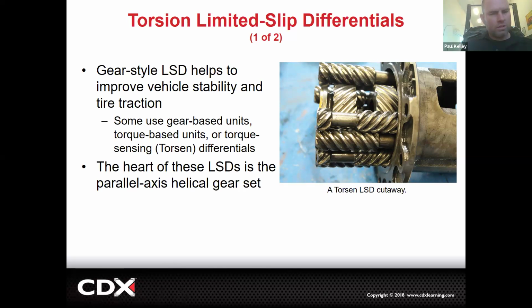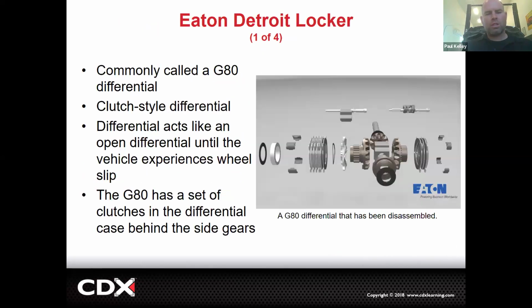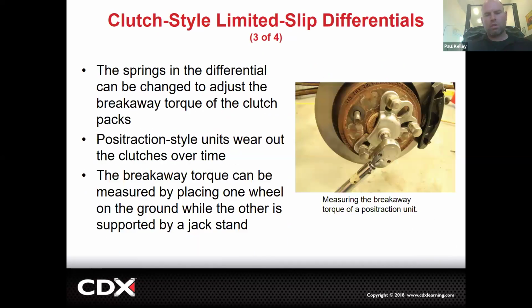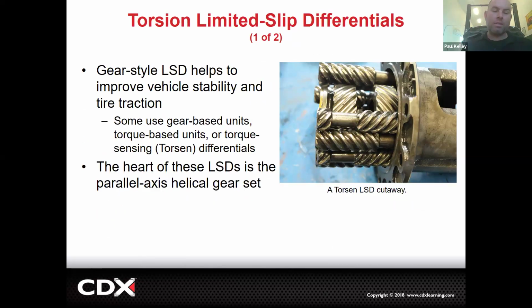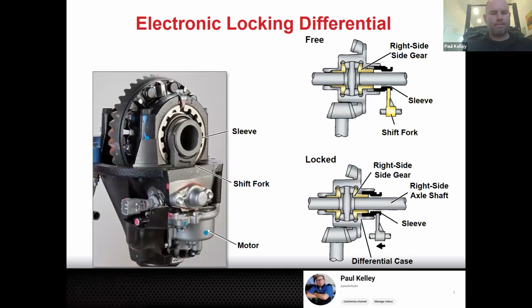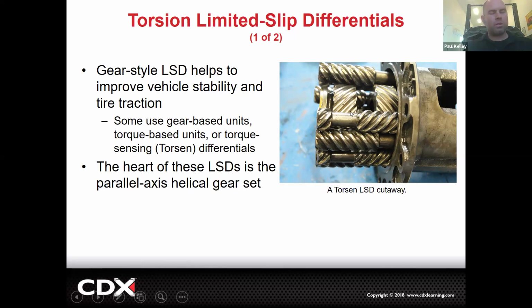So if there's no clutches, we don't need to worry about the clutches wearing out. The Torsen's amazing, and it's pretty ingenious, really. So if you go with a Torsen, you're not worried about clutches. All these other ones are clutches, clutches, clutches, and that's not bad. But the Torsen's pretty stinking nice, not gonna lie. The only thing I like better is a full e-locker. But this wouldn't be for a car. If it were for a car, I'd probably prefer the Torsen mostly.